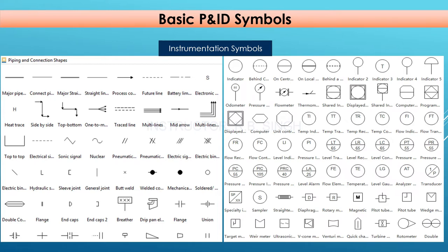In your P&ID there could be different types of instruments. Suppose flow meters. There could be different flow meters, for example, ultrasonic flow meter, magnetic flow meter, Coriolis mass flow meter, Venturi meter, pitot meter, orifice plate, restriction orifice. These are the main instruments used in your projects. So we must know by the symbol which type of flow meter it is.